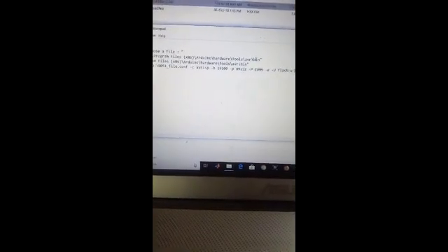First we would copy that file into D program, then change the directory, copy the file to that hardware AVR bin where the AVRDUDE is located.